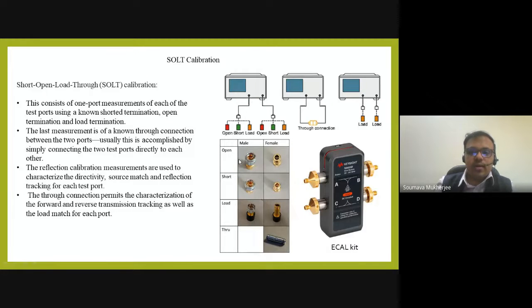Okay, and what it typically does: first it will connect the open and record the response, then short, then load in both the ports, and then through. Through means that from port 1 to port 2 they are connecting it and recording the result. So what it will do is that these are all standard loads, we all know.